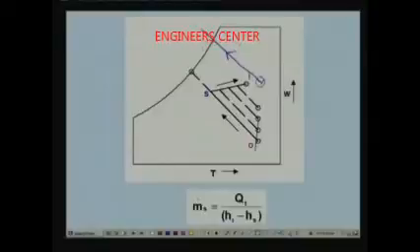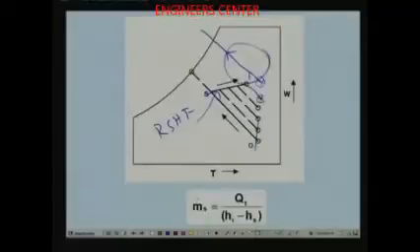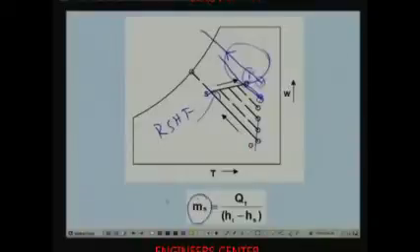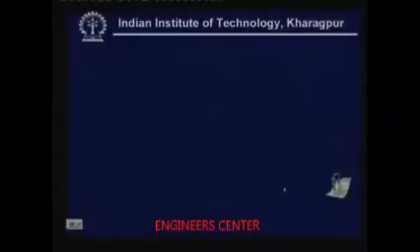That means it does not intersect the room sensible heat factor line at all. So you cannot use an evaporative cooler beyond a certain point. In fact, when the humidity ratio lies at this point, and the process line passes through the condition point I, you will find that the required amount of supply air is infinite. So beyond a certain humidity ratio, this system does not work. This is a very important thing one must keep in mind.